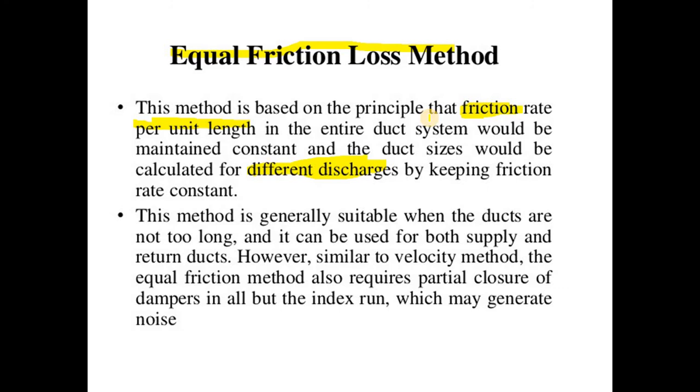So mostly the application of the equal friction method is to supply the air within short or small applications. That's why we must consider the effect of the velocity a little bit as well while designing with the equal friction method.